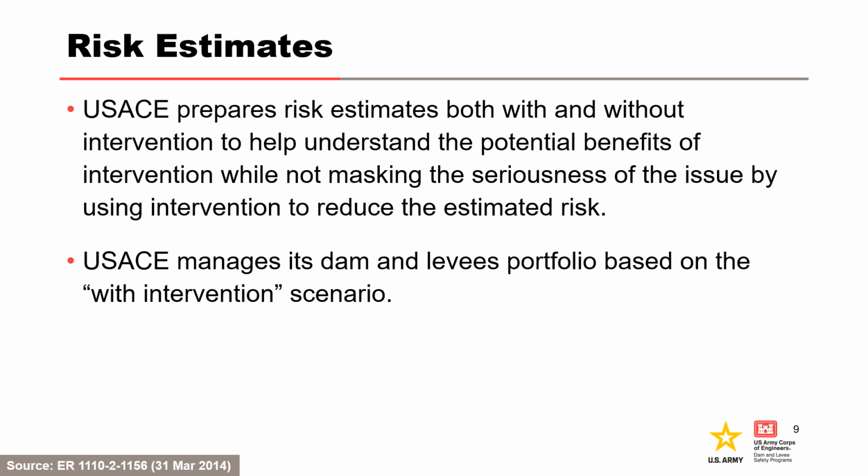USACE manages its dam and levee portfolio based on the with intervention scenario. When evaluating intervention, it's important to consider during the risk assessment specific actions that could be taken to prevent a failure and their likelihood of success. By and large, intervention efforts have been successful in our inventory, and it's common to see an order of magnitude or greater reduction in risk when intervention is considered.